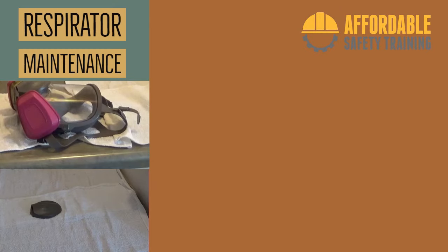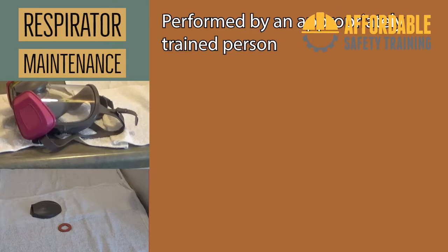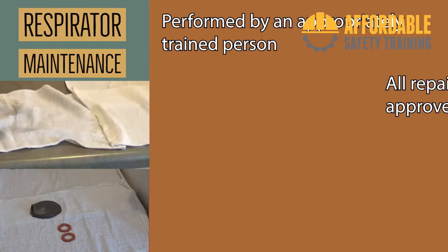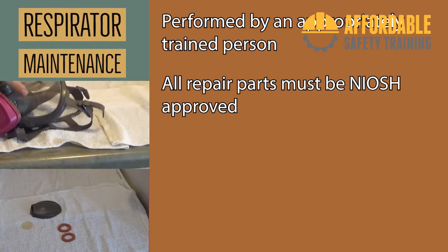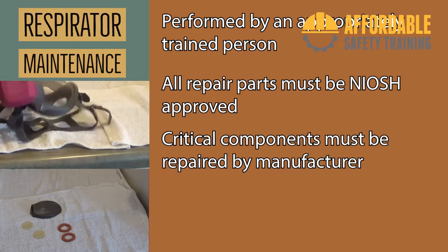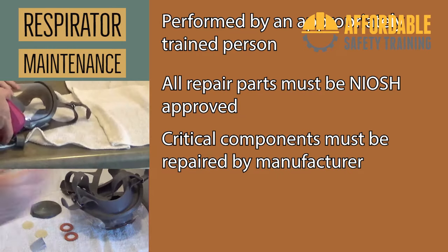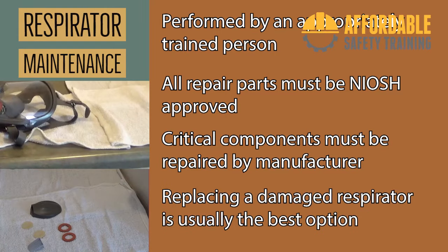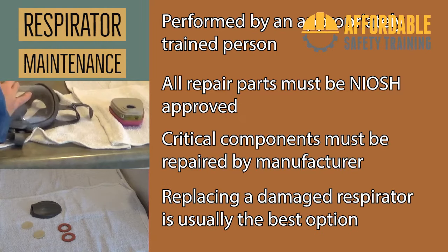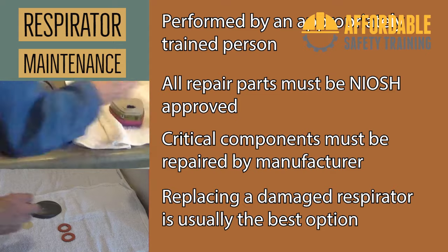Respirator maintenance should only be performed by appropriately trained persons. All repair parts must be NIOSH approved. Valves, regulators, alarms, and other critical components should only be repaired by the manufacturer. If a respirator requires repair, it usually is just easier to purchase a new one.